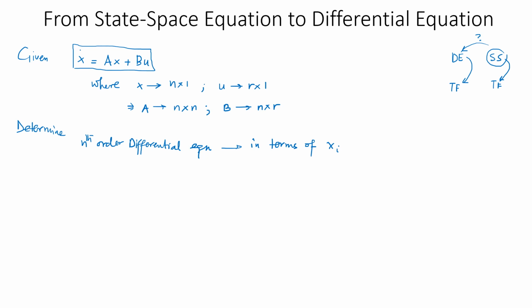Now in order to do that, what I can assume is that we can take the Laplace transformation of the state space model. So this is what we're going to do now: take this equation, which is equation A. Let me use a different notation so that you are not confused, let it be equation number 1. So 1 can be transformed into another equation using Laplace transformation. So this would mean that you can have sX equal to AX plus BU.